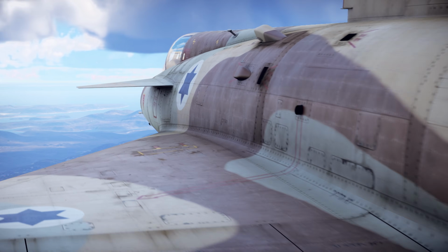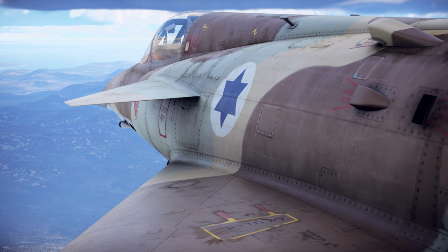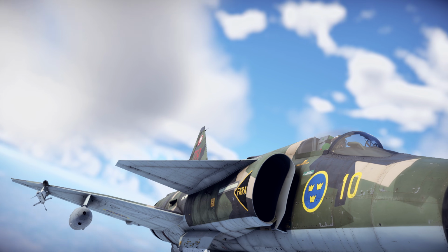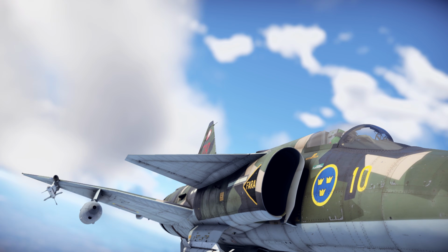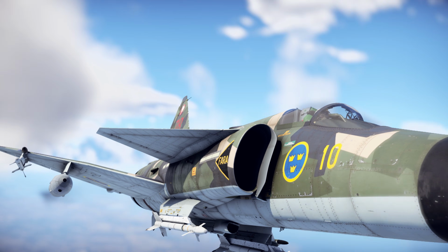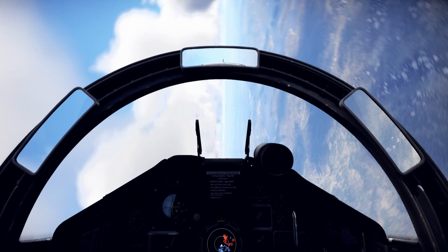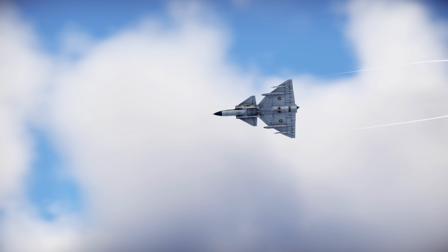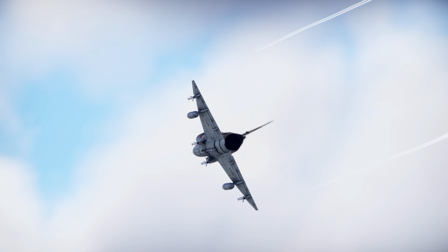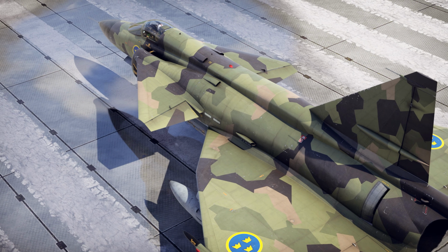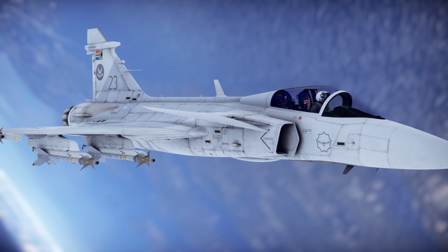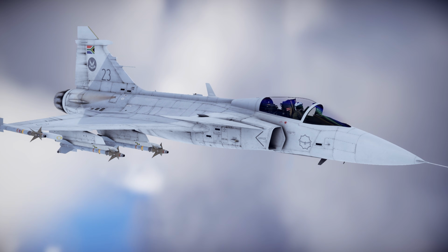An interesting case is the Canard configuration. In this setup, horizontal stabilizers are mounted on the nose of the aircraft. These stabilizers may be fixed and participate in generating vortices that increase lift. If the front control surfaces generate substantial lift themselves, they may be considered an additional wing. An example of such a design is the Swedish Viggen, which even has flaps on its front stabilizers.